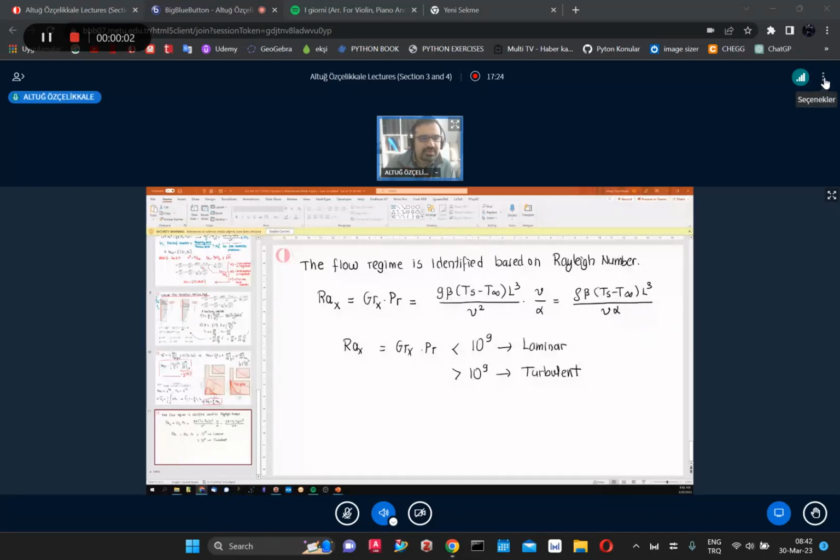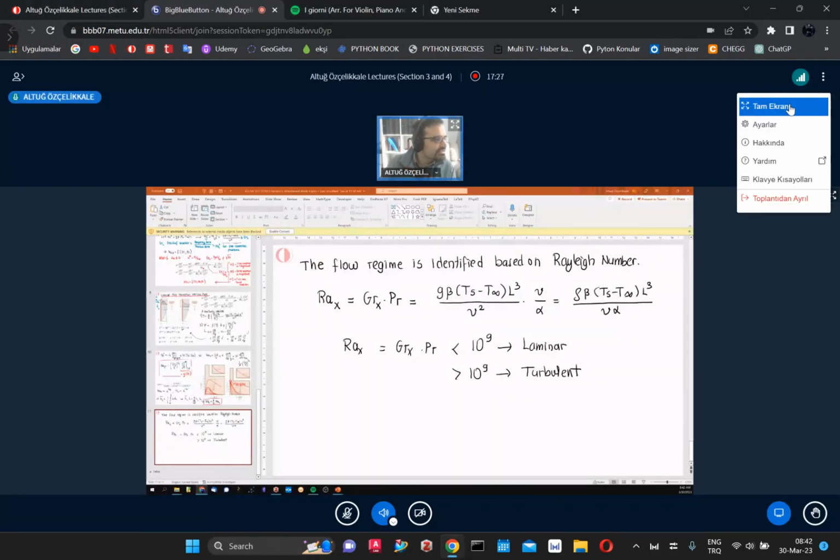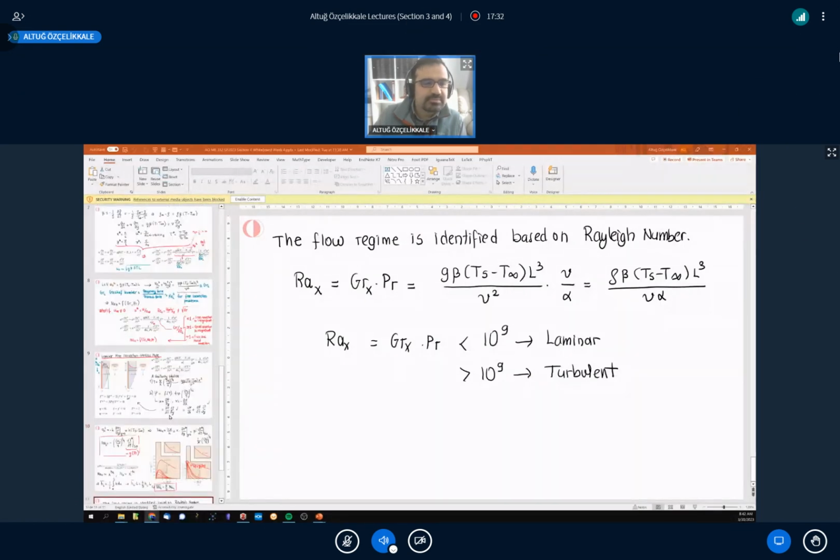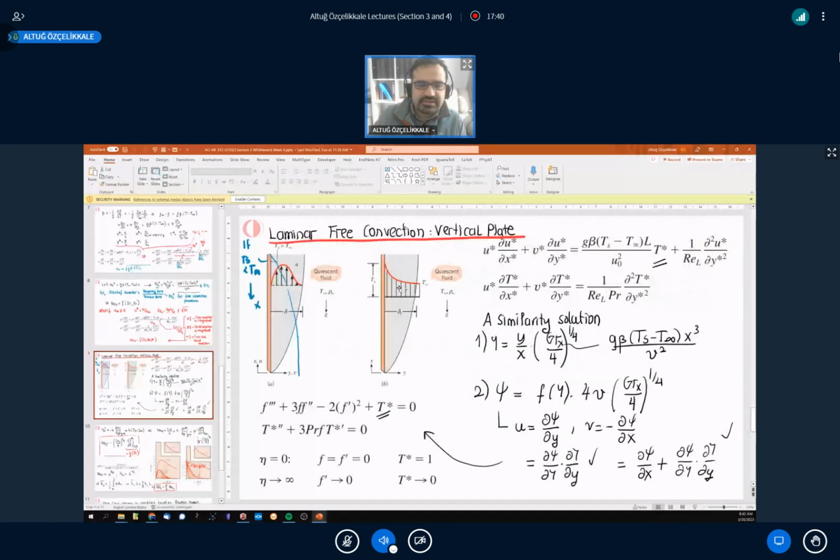All right, okay, so what were we doing last time? We started our discussion of free convection, and particularly we talked about the boundary layer phenomena, and we did a similarity solution. We covered the similarity solution for a vertical plate, and the solution involved solving hydrodynamic and thermal boundary layer together. They are coupled because of this temperature term. This temperature term gave rise, remember, to the buoyancy forces, the density variations, resulting in buoyancy forces. Therefore, it was part of the momentum equation as well.